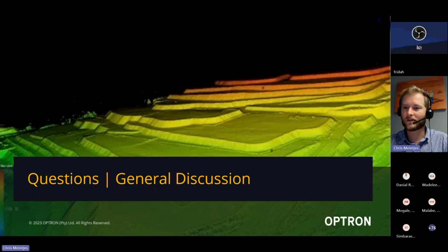Phalos, I see you just got a question that came through there. Yes, if you've scanned, for example, one area and it's georeferenced and it's sitting on the right system, and then a week later you come and scan again and you overlap them, you can very much in TBC and RealWorks have this in a project, bring the scan into the project, and if there's enough overlap between the two, register that point cloud on, and it should be on the same system. Obviously, that is dangerous. The further on you go, you will start to experience drifts. So it's good to control your point cloud every now and then just to make sure that it's still heading in the right direction.